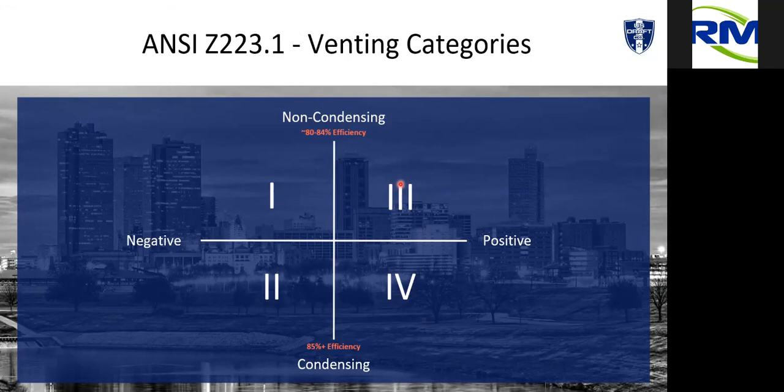It is a non-condensing appliance, but in certain applications, it can be a condensing flue system, because the boiler is not designed to condense. The Futura 3 is actually the one I was speaking of, excuse me. But that's in that upper 80s efficiency. So where the boiler is not designed to condense inside the chamber, but the flue temperatures are such that they do have potential of condensing in the stack. So that 85 plus kind of 86% is typically what we see as that break point.